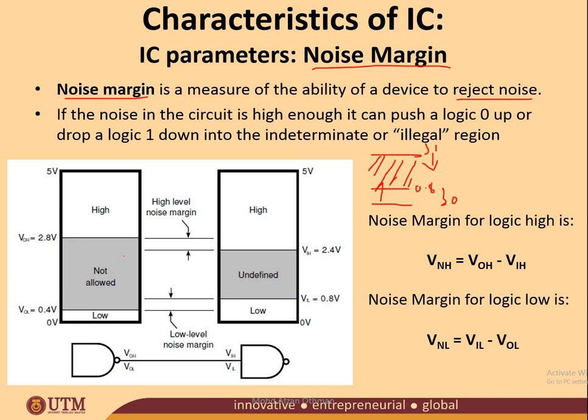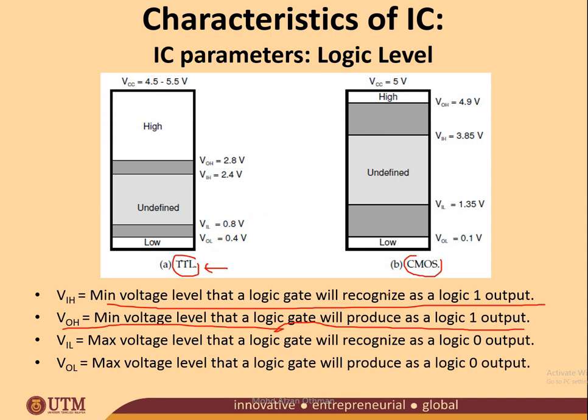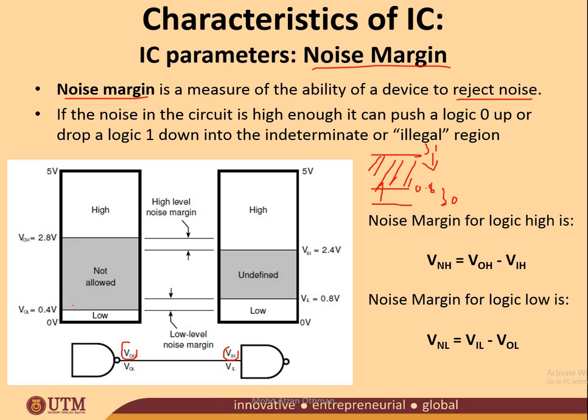So let me see from here. You see this is your VOH and this is VIH. This is output and this is input. Maybe you are wondering, these have the same wording, right? In the next slide it's explained. So this is the output VOH, and this is the input VIH, and you have VOL, which is the output low to be regarded as logic 0, and the corresponding input low VIL to be considered as logic 0.